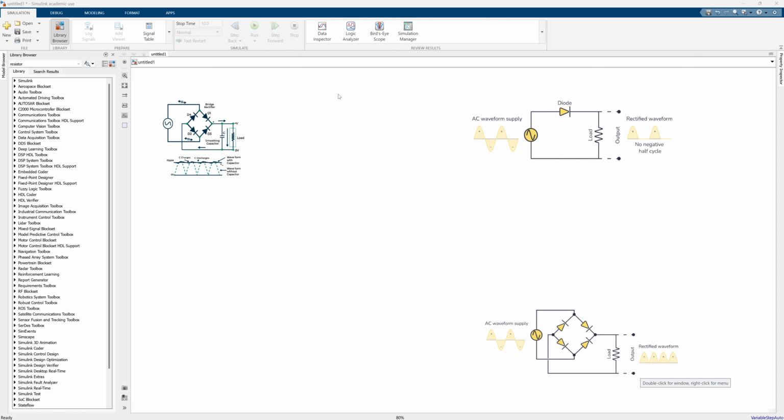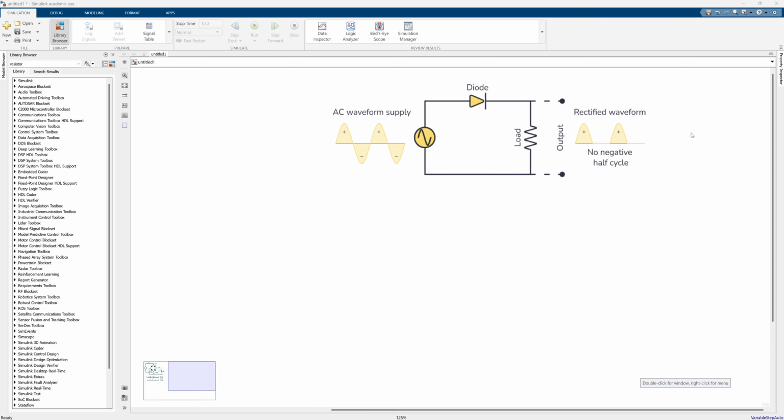Today we want to talk about rectifiers. In this lecture we are using diodes, just bridge rectifiers. When we talk about rectifiers, it means that we want to change the AC waveform to a DC waveform, and the component that we have is the diode. We can also use thyristors or IGBTs, but today we want to use the simple one, the diode.